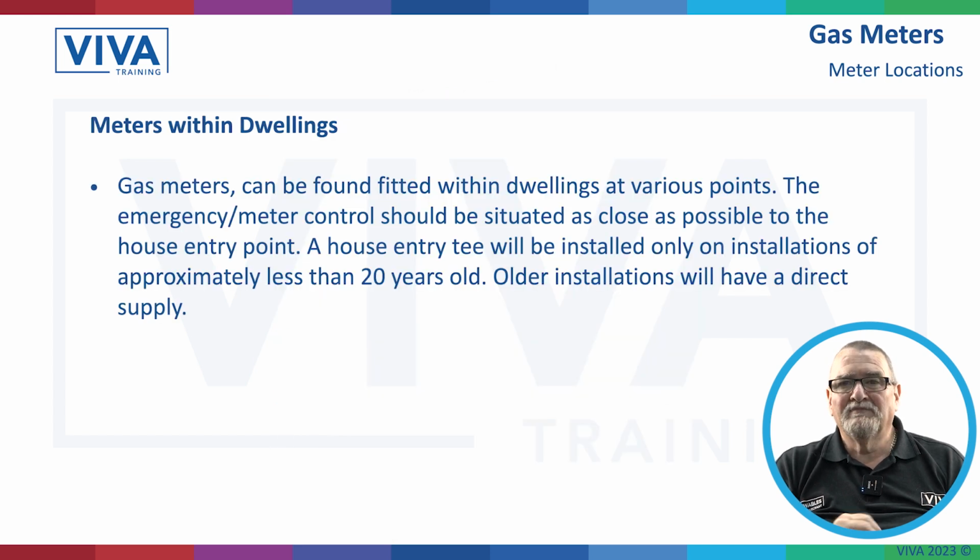Now, gas meters can be fitted in properties, and they were for years and years and years. When I first started in the industry, most gas meters I went to, they were in the cellar, they were under the stairs, they were inside the property, and we can still come across them because there are still meters there. They're all over the place, and again, the ECV has always got to be accessible, so if it's under the stairs and somebody's thrown lots and lots of things in, we've got to explain to the customer we need access to that ECV, because if there's an emergency, they need to turn it off as quickly as possible.